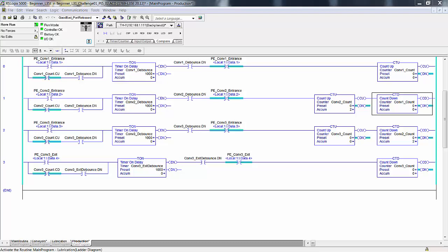Okay, with 1 PE and 1 motor, each conveyor can pass through, which is pass the carton through to the next conveyor or station, or it can buffer. Stop the conveyor for each carton that has traveled onto the conveyor and wait for the next carton to arrive, as seen in step 2 on the previous page. Each conveyor can be programmed to do either as production calls for it.